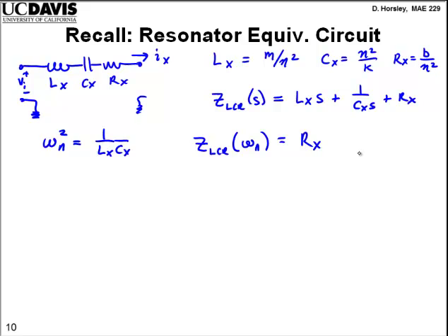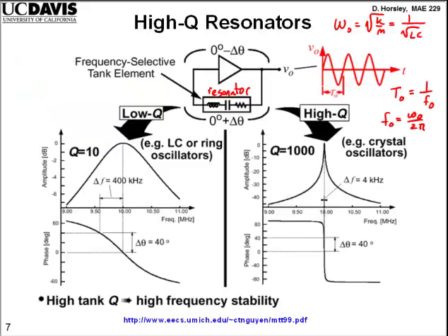And you'll notice also that we could think about this if you look at this impedance, right? You remember I plotted the frequency response of the LCR tank. If we go back to this, we looked at this amplitude here and this phase. So at resonance, it has 0 degrees of phase, right?